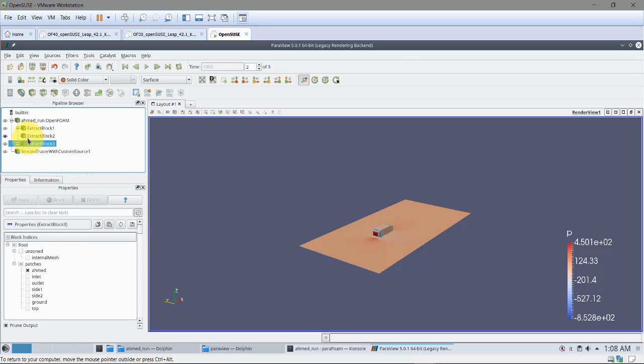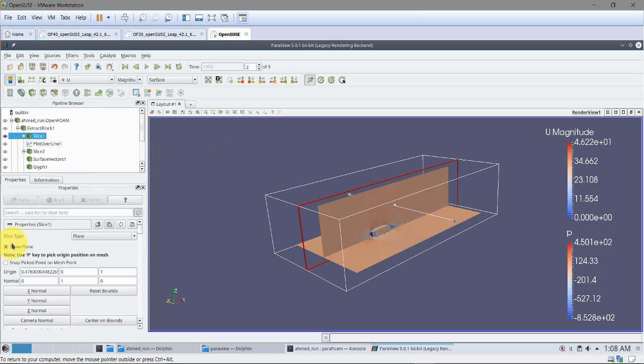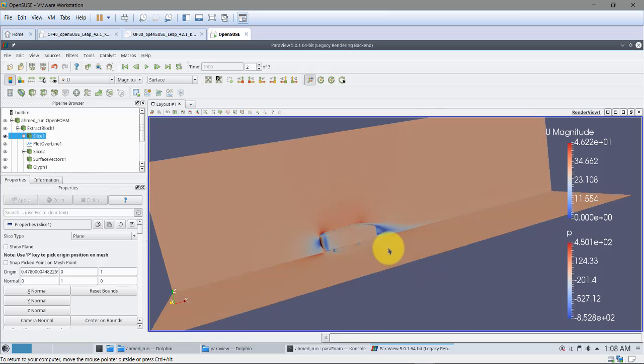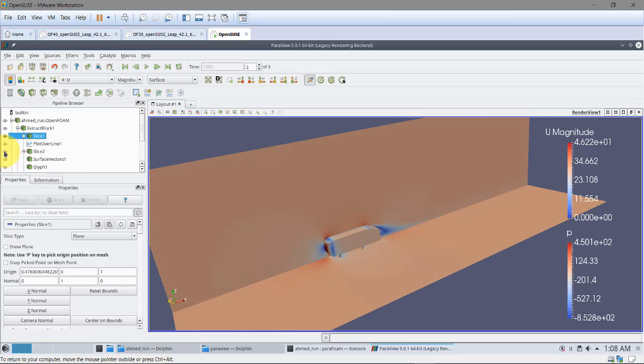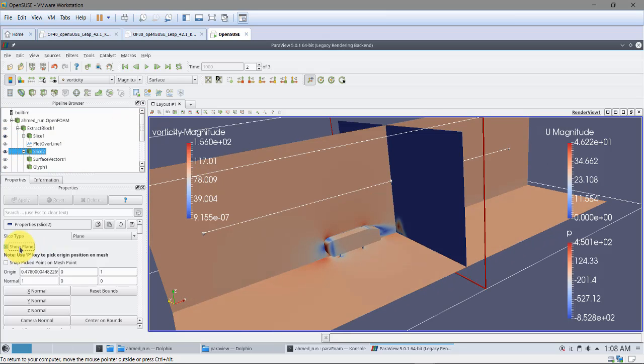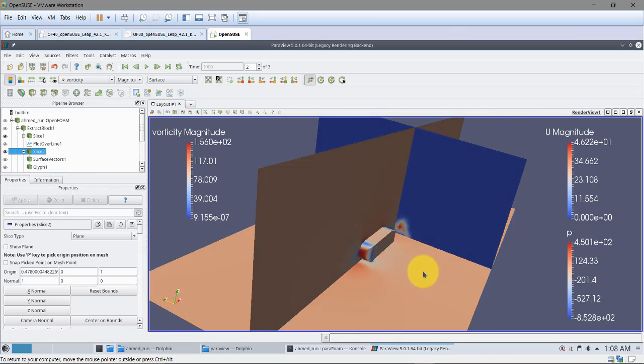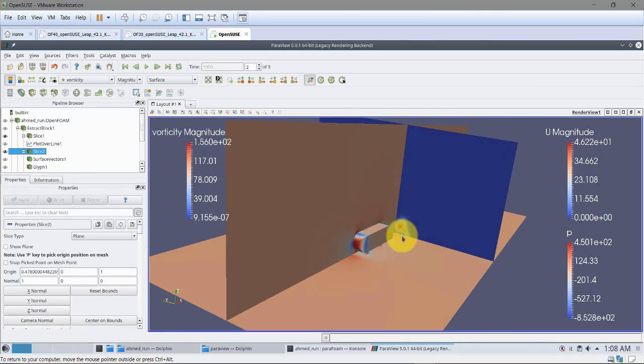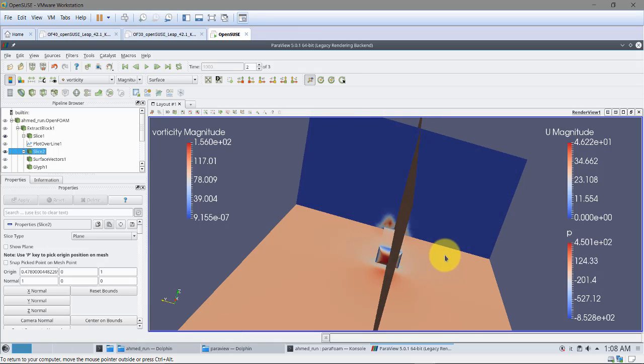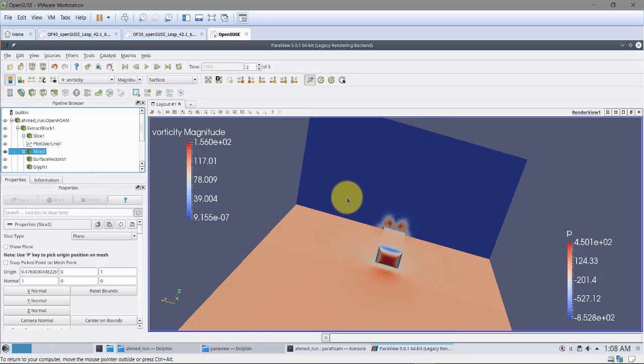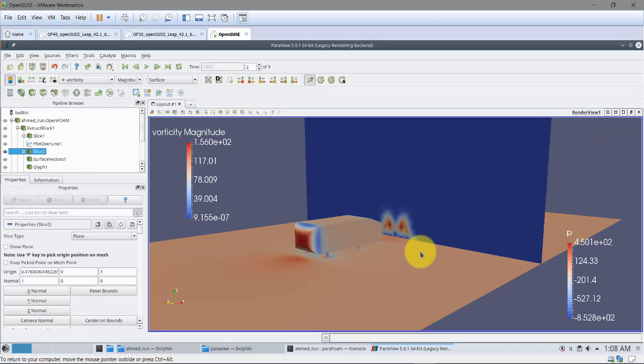So I extracted this tree and I'm planning to do some operations in those blocks that I have. For instance, in block 2, look at that, I have slices. So I have those 2 slices there. In this one I can plot the velocity, and then I have a second slice where I can plot whatever I want. So it doesn't necessarily need to be the same field. Look at it here, I'm plotting vorticity, and here vorticity gives you kind of an indication of the rotation.